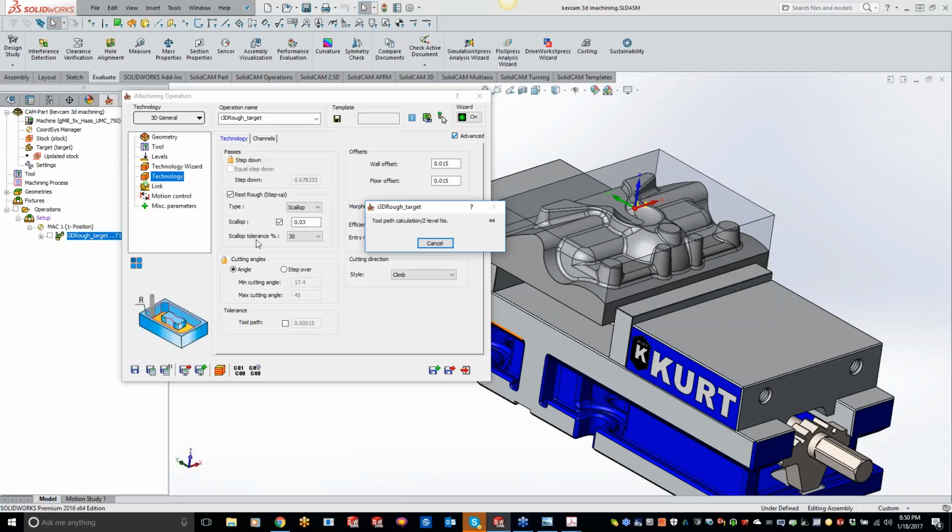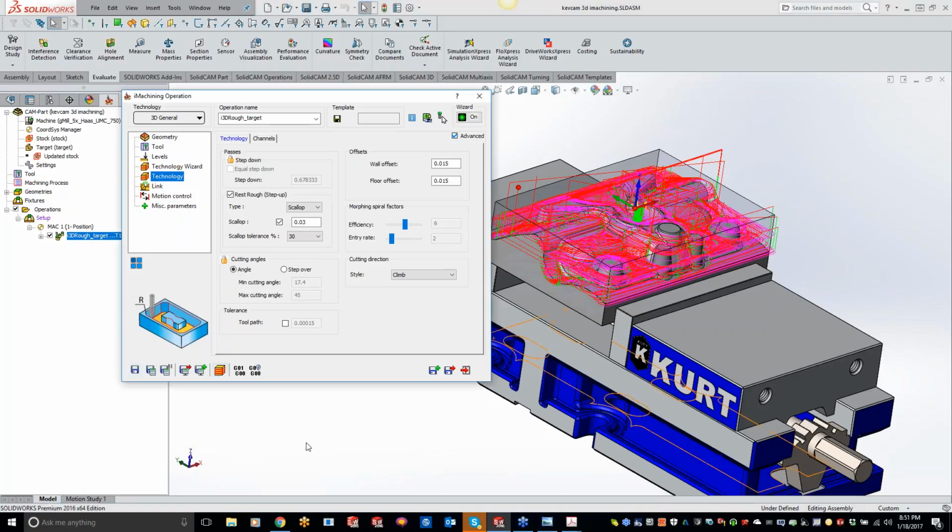So we had a great question last week. The most that you will ever be able to engage a cutter is going to be 80, I think it's 85 degrees. Well, this particular customer wanted to go farther, 110 degrees. And this is where we can change that, the angle of engagement. So you're not locked out of it, but you're not going to have the wizard backing you up with the correct feed rates just because we're over engaging that end mill. Okay, let's get some toolpath here. And I might have to simulate this just so you guys can see the difference.